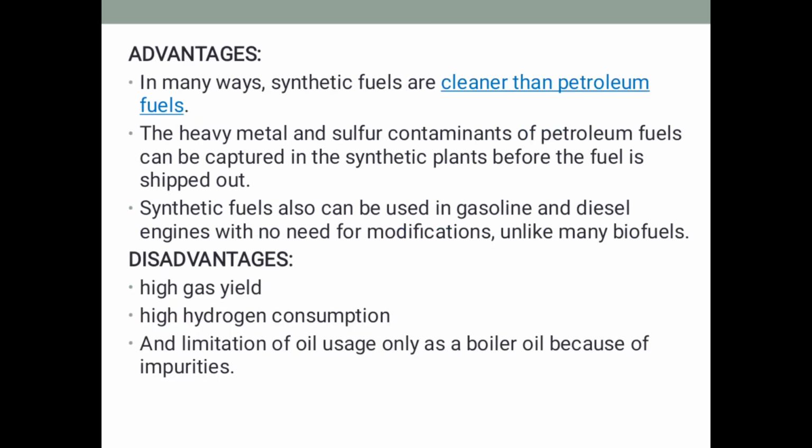Advantages. In many ways, synthetic fuels are cleaner than petroleum fuels. The heavier metal and sulfur contaminants of petroleum fuels can be captured in the synthetic plants before the fuel is shipped out. Synthetic fuels also can be used in gasoline and diesel engines with no need for modifications, unlike many biofuels. Disadvantages: high gas yield, high hydrogen consumption, and limitation of oil usage only as a boiler oil because of impurities.